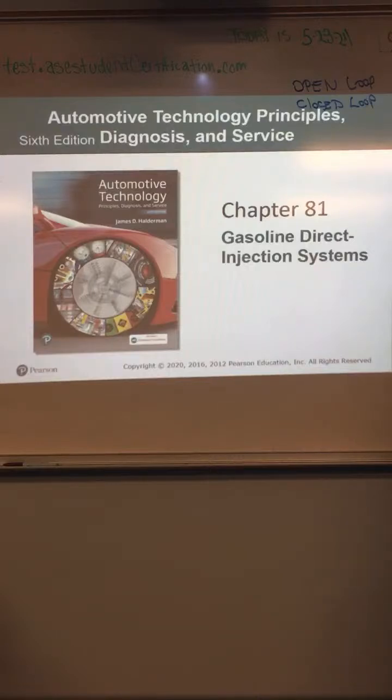Fuel injector is basically a solenoid, right? Opens and closes. What does it normally take to operate something like that? At least the system voltage on the vehicle, right? 12 to 14 or 15, depending on whether the engine's running or not. So that's just a standard thing you need to know, not something that would necessarily be in the book.